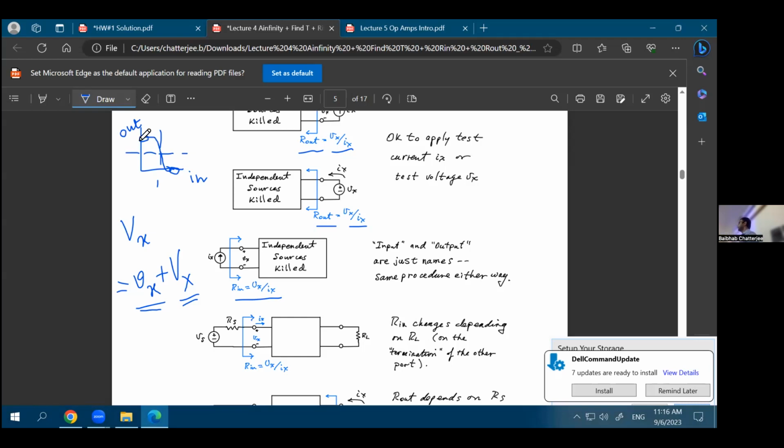So this is called the voltage rail. This is usually very close to the VDD or the supply rail, and this is usually very close to the ground rail, right? So the value in the y-axis I'm talking about: this is the supply rail, which means it has a high value, and this is the ground rail, which means it has a low value. Whenever you are in the middle of the rails, so if you have a 5 volt supply and a 0 volt ground, whenever your DC point is around 2.5 volts, you can expect quite a significant amount of gain from your amplifier.